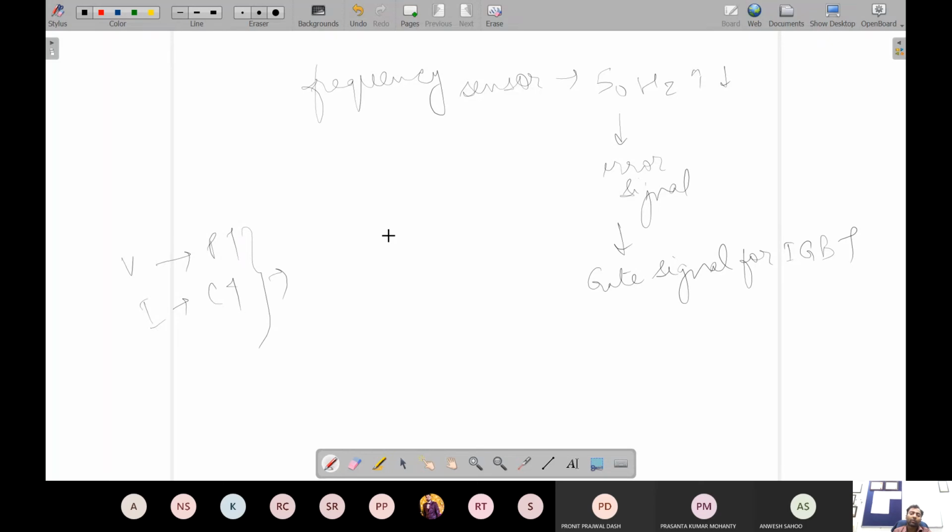And why we are doing this is because we want to detect any imbalance in the phases. You have a three-phase system, so there is some VA or corresponding current, IA, IB, and IC. There is a possibility that the magnitude of one of these is lesser than the others. This is what an imbalance system would look like, and we don't want this type of imbalance, because that creates complexity in the operation of the system.